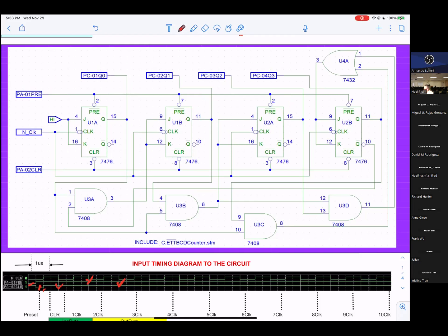Okay, still not done yet. If you test the 4 preset, you apply 0 here, and that will be 1. And now you get the static fail. When you check the U1 pin 2, pin 7, they are on logic 0. They are 0. But they still fail. Tell me what next you want to do.